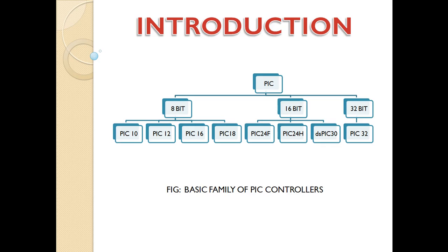at a time. Depending upon the different capabilities and list of functions an IC can perform, these categories are again divided into subcategories. PIC10, 12, 16 and 18 all come under the 8-bit categories. That is, all these ICs will process 8-bit data at a time, but all have the advanced functioning than the others.